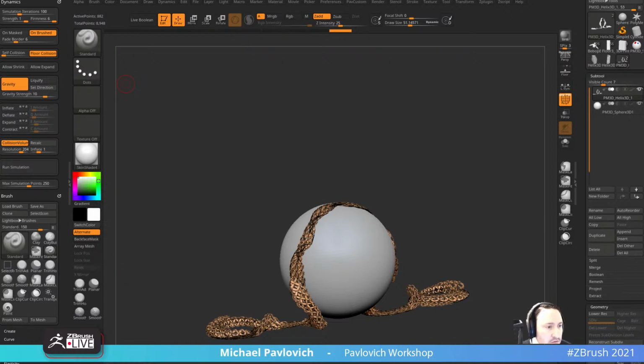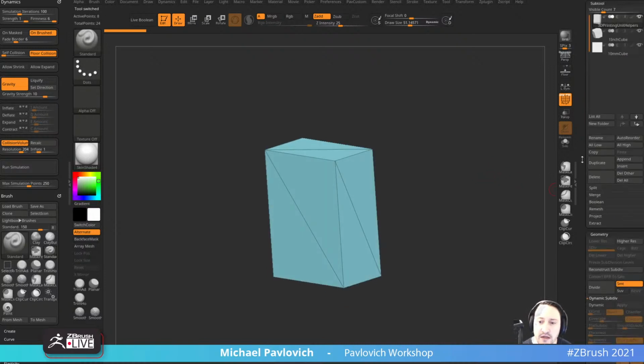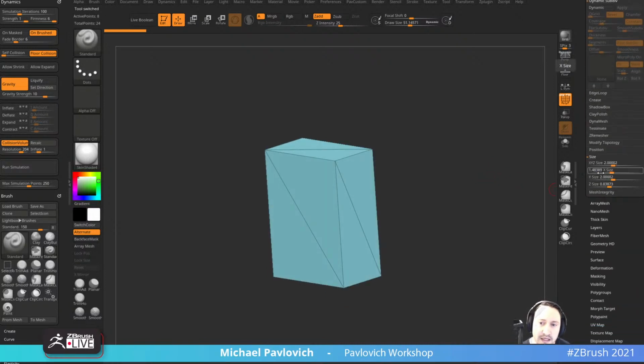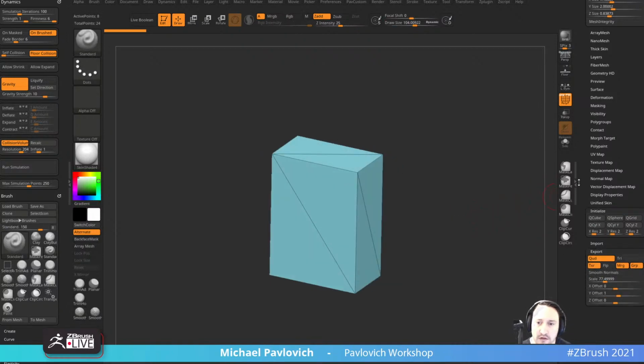And make sure that when you export your model from ZBrush, Maya, Blender, or 3ds Max, it's the exact same size. Oftentimes the model is super small. The easiest way, if you're working at a certain scale in another program, is to bring in a 1 unit object exported from that program into ZBrush, and it'll do that automatically. It's exactly what I was talking about when I brought these in. I made these in Fusion 360, imported them, and it did those conversions for me. It keeps it at ZBrush scale here at 2, so it works nicely. And down here, it's going to add export scale, so when I export it, it's good to go.